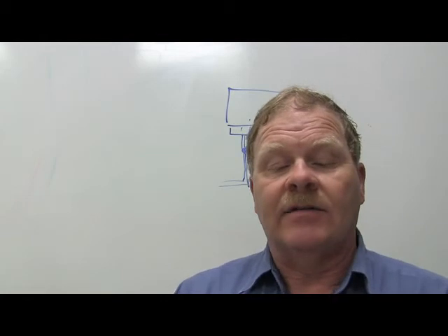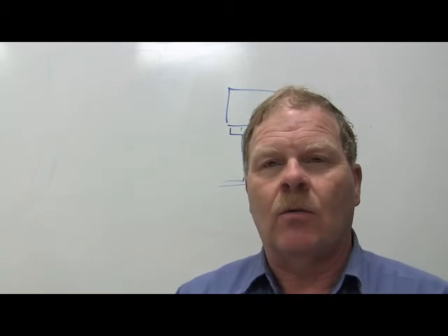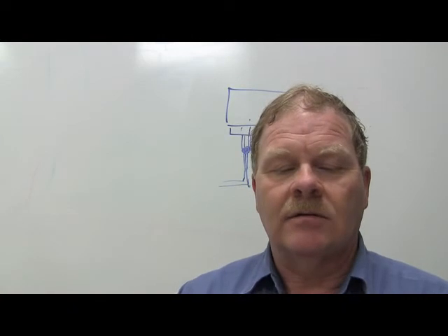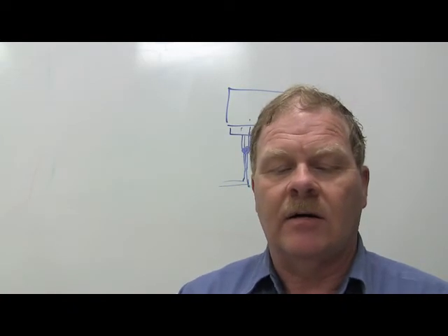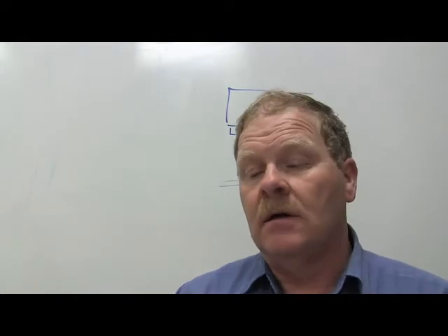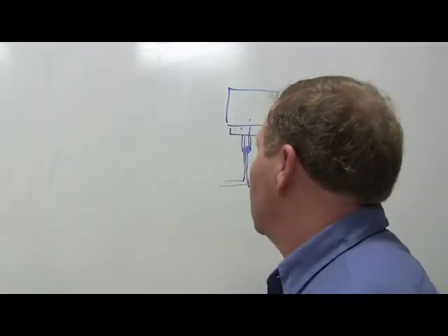Let's see. Technician A says the effect of temperature on resistance is a factor in wire size selection. Technician B says wire must be large enough to carry the amount of current necessary for the circuit to operate correctly. Who's right about that? That's going to be C. If you've got